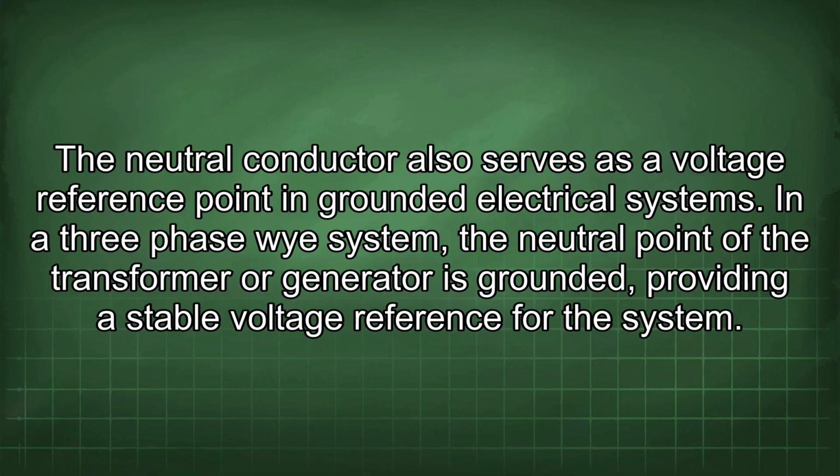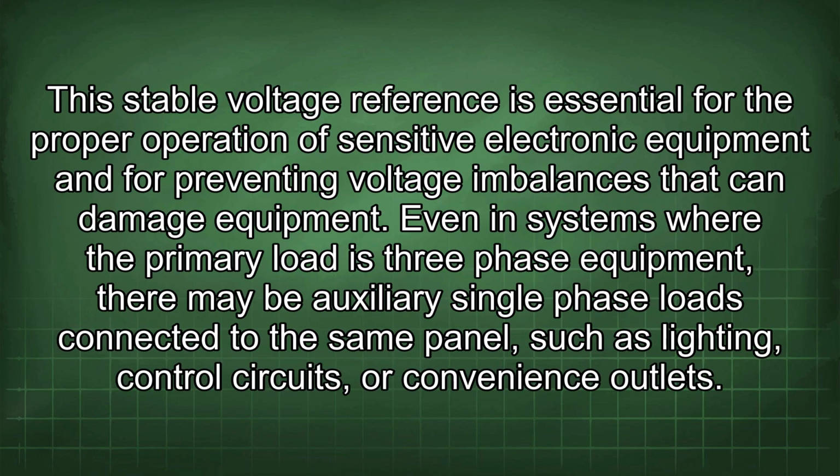The neutral conductor also serves as a voltage reference point in grounded electrical systems. In a three-phase Y system, the neutral point of the transformer or generator is grounded, providing a stable voltage reference for the system. This stable voltage reference is essential for the proper operation of sensitive electronic equipment and for preventing voltage imbalances that can damage equipment.